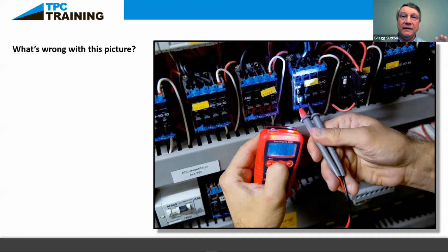Let's see here. In this case, instead of drawing on here, let's put text. So student Ryan here, I'll type for you. What do you think is wrong with this picture? Are there any mistakes being made? Yeah, I definitely see the guy is testing without wearing gloves. So no gloves. Good. Anything else bother you? I see that meter is probably not the correct quality. Yeah, when you're getting 300-400 volts, 480 volts, you probably ought to have a good meter.